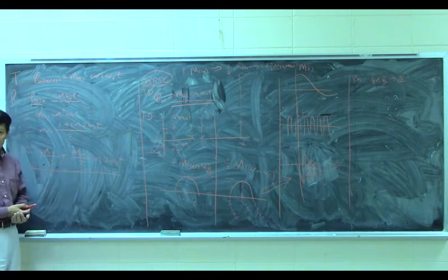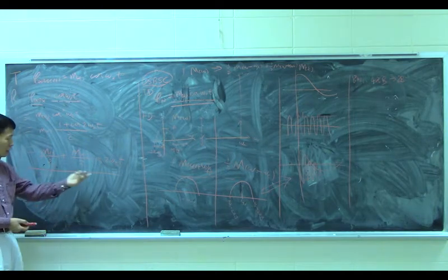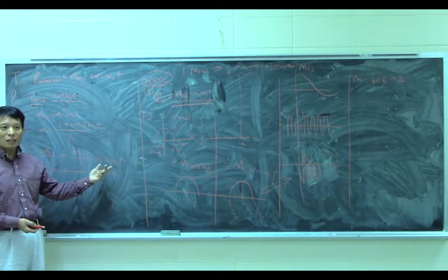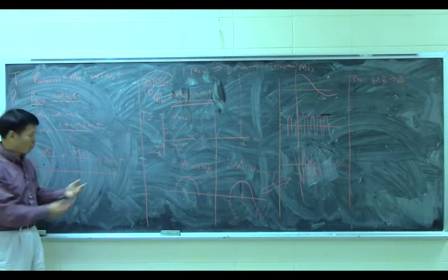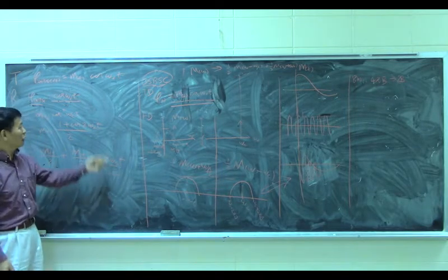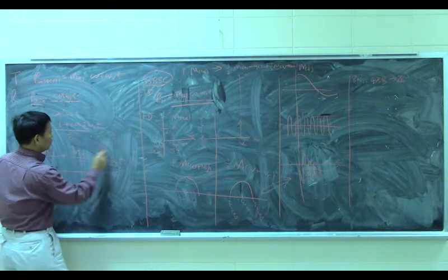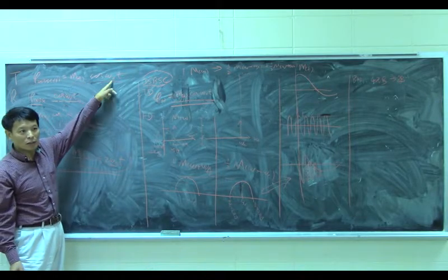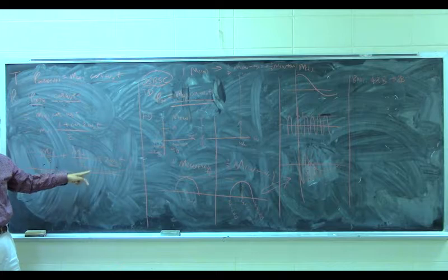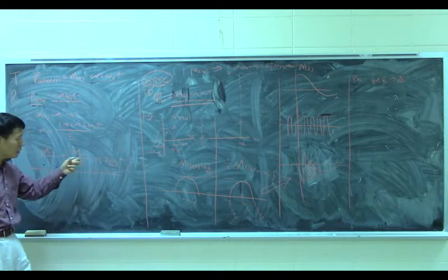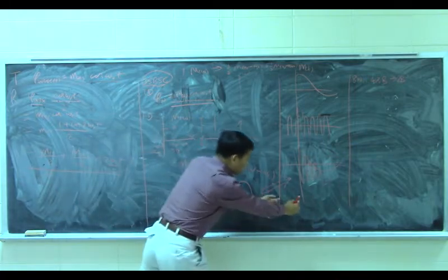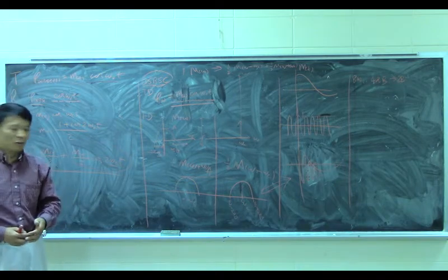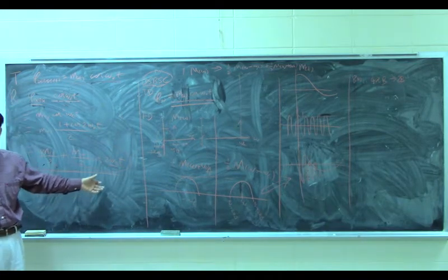So that is what we want. What is this one? Look at this: m(t) times cosine 2 omega_c t. What is this signal? This is also a modulated signal, right? The frequency is 2 omega_c instead of omega_c. This is a modulated signal at omega_c, and this is also a modulated signal, but at 2 omega_c. So the spectrum of this will be shifted even further to the right, to 2 omega_c. That means the frequency is even higher. Maybe even the dolphin cannot hear this anymore.